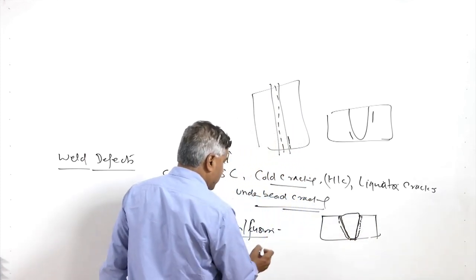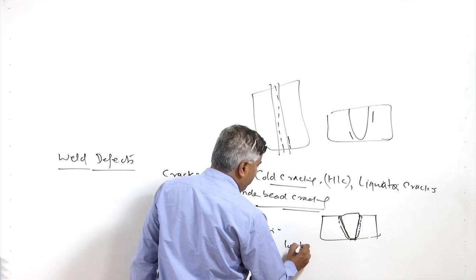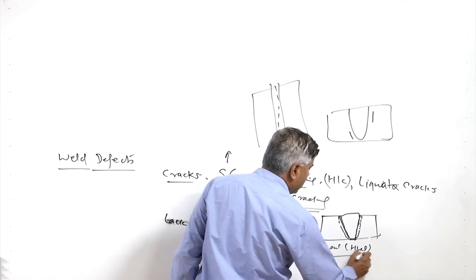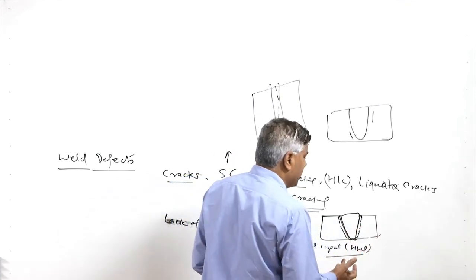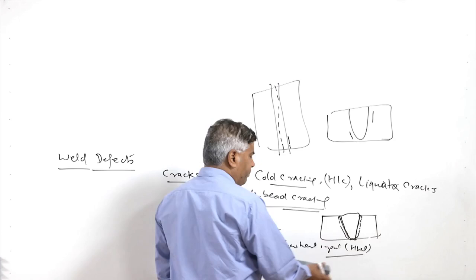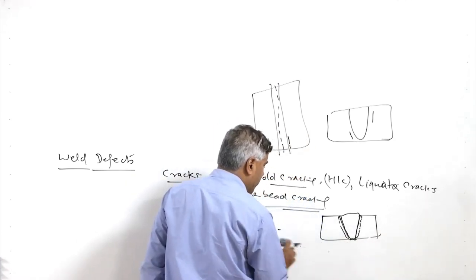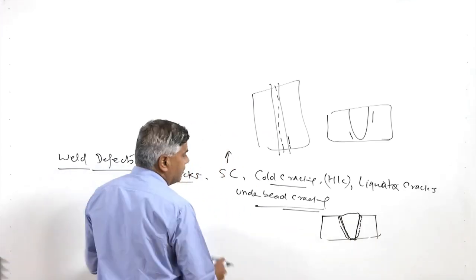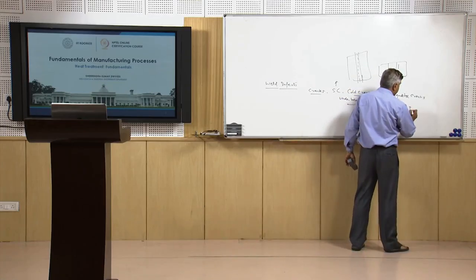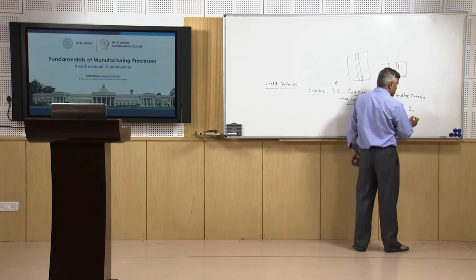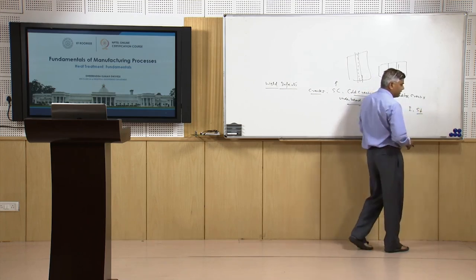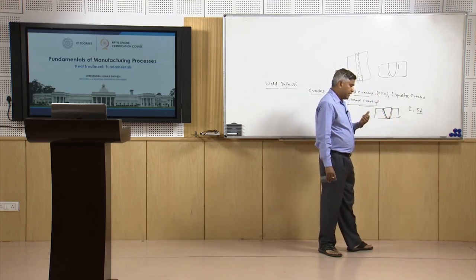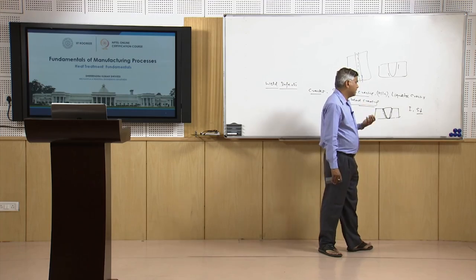Both these kinds of defects are caused by low heat input, or less net heat than the required value, which leads to deficient or limited melting of the base metal, or no melting of the base metal, with just molten metal getting deposited over the surface. This kind of defect is simply taken care of by increasing the welding current in case of arc welding, or by slowing down the source of heat, whether it is the laser beam, electron beam, arc speed or the flame speed.